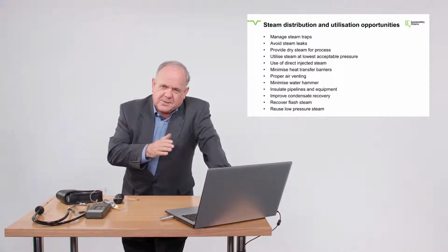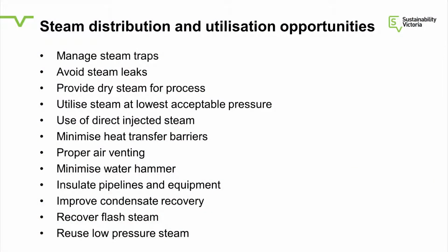That's enough about steam generation. Steam generation, a modern natural gas boiler, if it's tuned well, is 80% efficient. So for one unit of energy going in as gas, 0.8 goes out in steam or hot water, so it's pretty good. In a condensing boiler for hot water, that might be up to 90%. So they're pretty good.